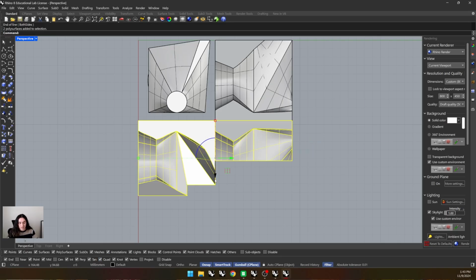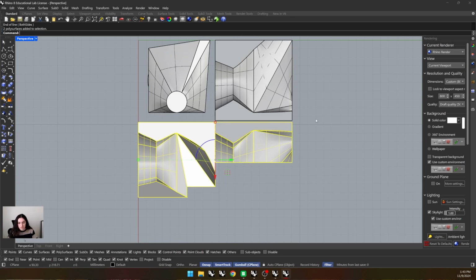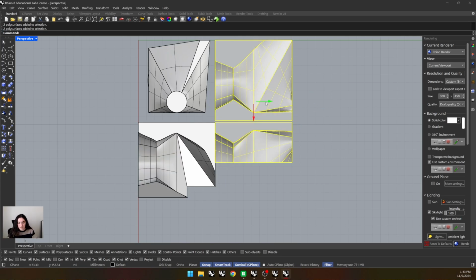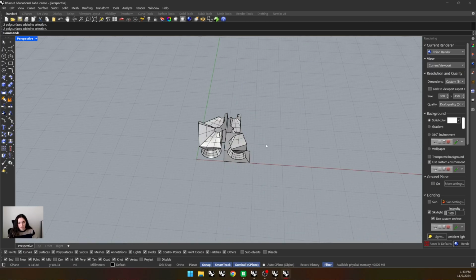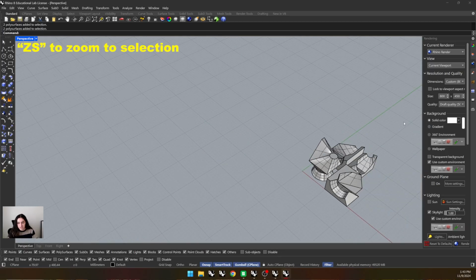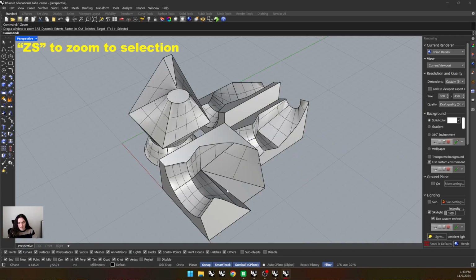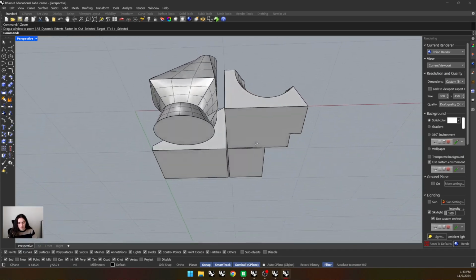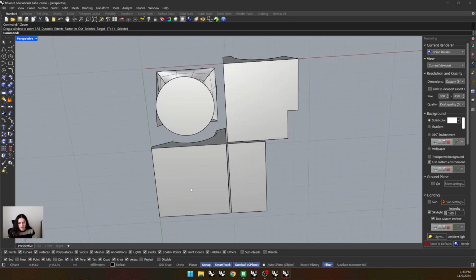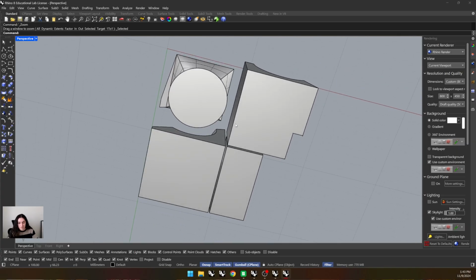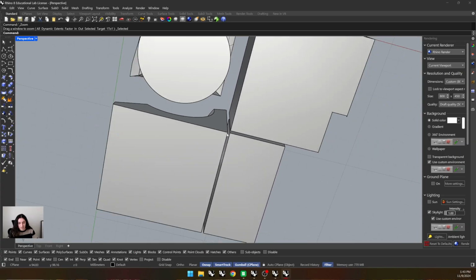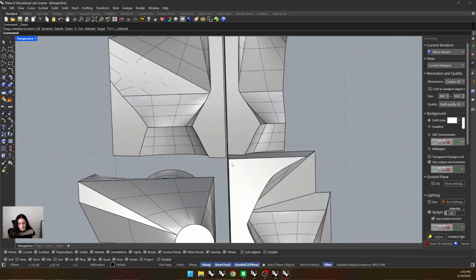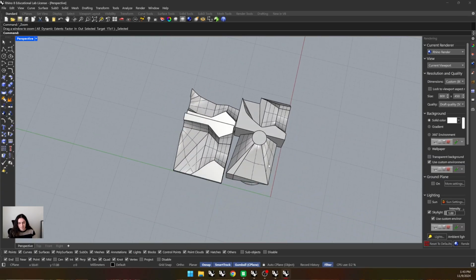I'm just going to move these apart so they're not actually touching. So I'll move over 2 millimeters in both directions. So for all of you as you're printing, this is kind of the process you'll go through. You'll want to have 1, 2, 3, 4 prints on the bed at a time, but they need to be spaced out at least by like 1 millimeter or 2 millimeters, maybe 2 to be safe.